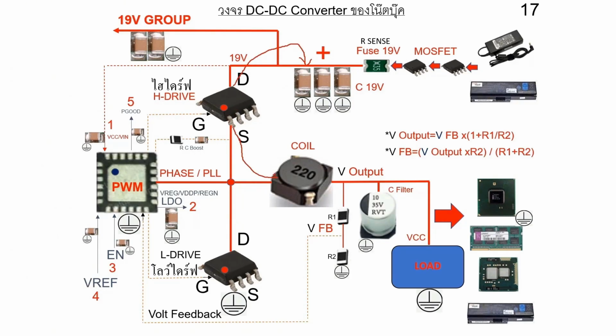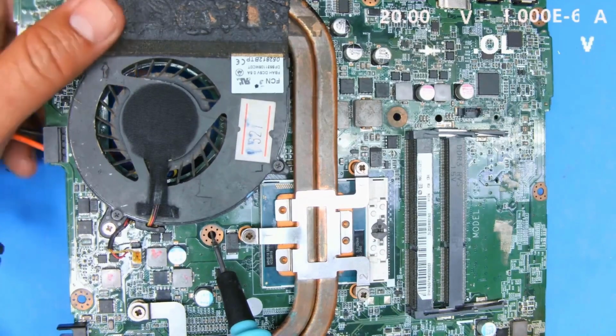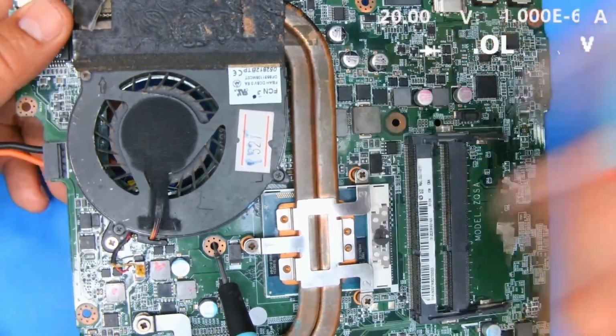As for its source pin, it connects to the coil. So we should measure across the 49 and the coil. This is how you measure the high side MOSFET output without having to power it up. Just use a multimeter to measure it. I'll try both methods. First, I'll supply just about 1.2 volts to see if it detects a fake short. Don't supply more voltage than that. If it doesn't detect anything, then just use the multimeter method. I'll use the measurement method first before powering it up to see what the result is.